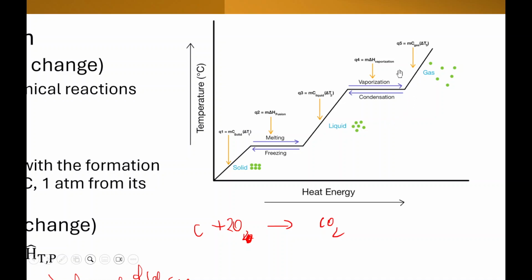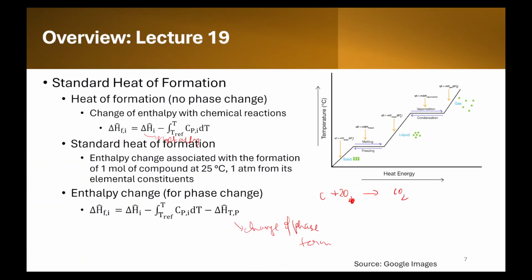At that point, the temperature remains constant and the heat energy keeps on increasing because this is the addition of latent heat. And then again in gas, you can keep on increasing the temperature. So that is how you understand the heat content can be either through the sensible heat, or through the latent heat, which is at a constant temperature and is due to the phase change.